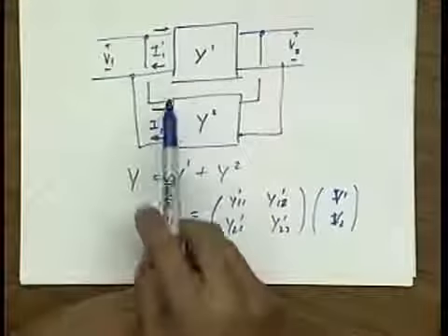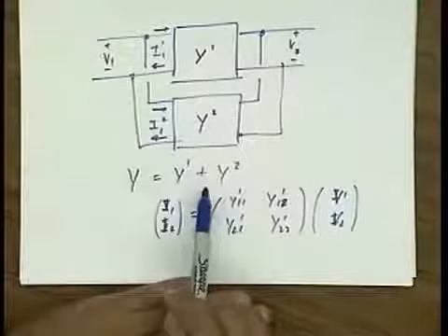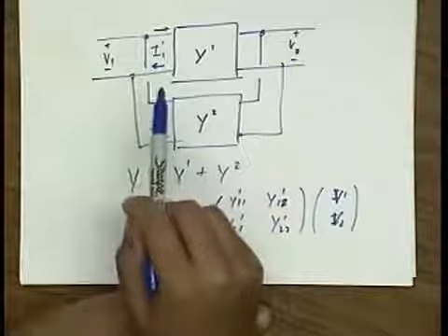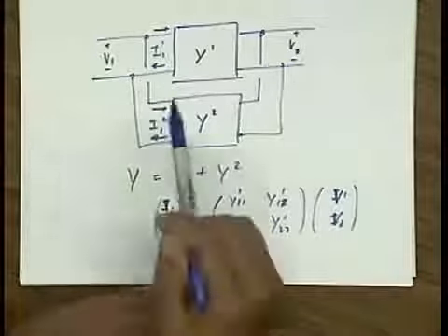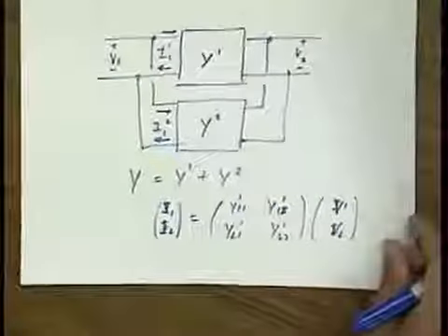So, in a like manner, if I were to connect these two ports in series, then I would sum Z parameters. And if I take the input in series and the output in shunt, or vice versa, I use the G or H parameters. Okay.